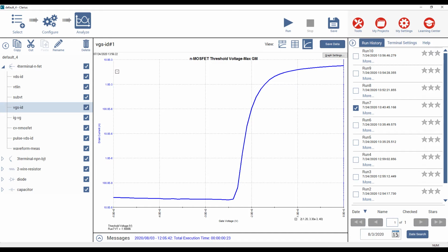So we can see that in the off state, this device is currently showing an off current that is in the nanoamp range, and in the on state, it turns on by several orders of magnitude and ends in the 10 milliamps range. The transition point at which the current starts to increase significantly occurs at around -2.5 volts.